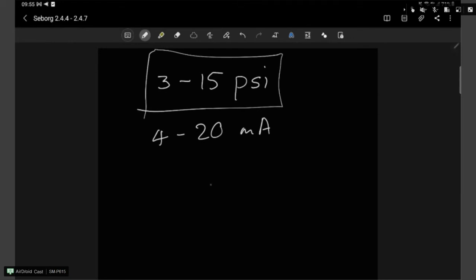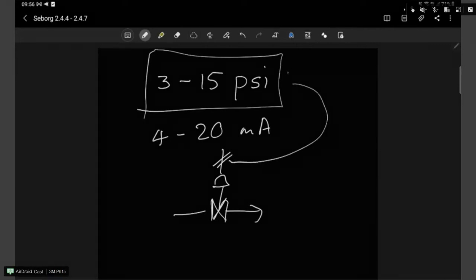A lot of the control valves that we use in industry are pneumatic control valves. So there's an air pressure signal on top of that diaphragm, and this air pressure signal is always in the range of 3 to 15 psi. So obviously, if we convert that to a kPa or bar unit, there are going to be decimals after that.